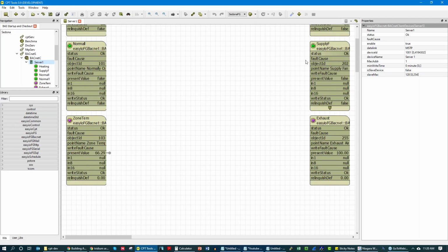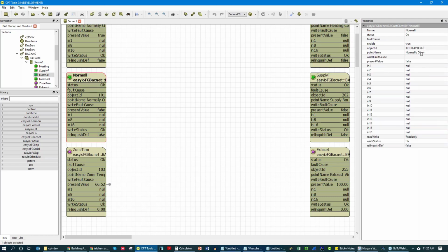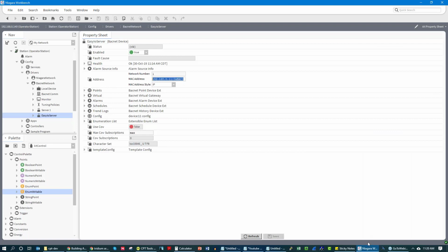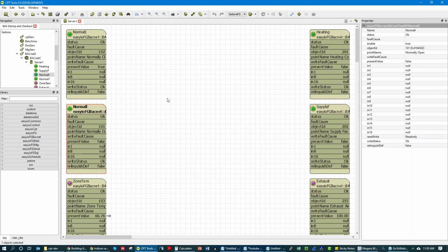And we can see that these BACnet points are actually tied to physical points. So if I were to command these BACnet points via Niagara over here, they would actually affect the physical points. Now I know we're just blazing by this at the 30,000 foot view, but this is what you do within the world of building automation.